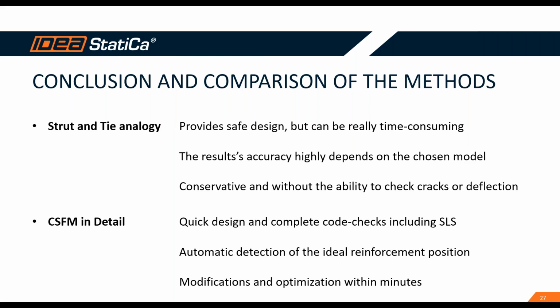And here is a little comparison of the two methods. The Strut-and-Tie analogy provides a safe design, and while it is safe, it can also be really time-consuming because you saw that the engineer had to create several Strut-and-Tie models to make sure he was designing safely and according to the behavior of the structure. And the results accuracy is also depending on the chosen model. The method is also quite conservative and it cannot check the crack widths or the deflections, which can also be quite important for engineers. The compatible stress field method in detail, on the other hand, provides a quick design and